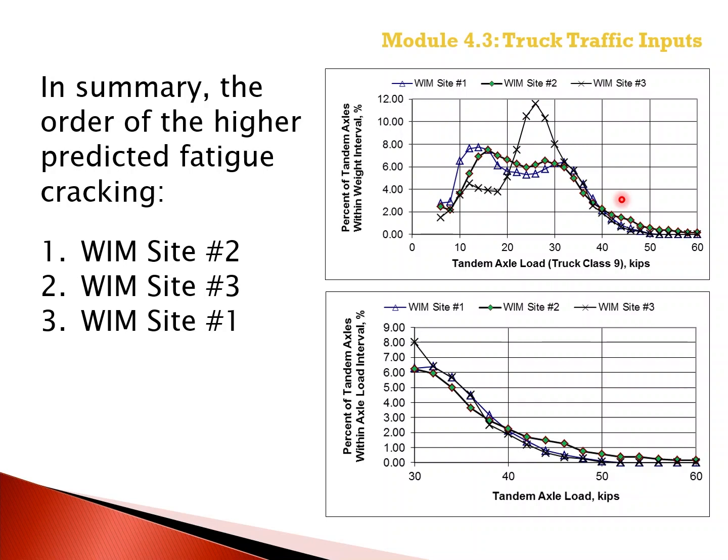So, do we have to have the same precision through all load levels for pavement design? The answer to that question would be no. We'd want the higher precision at the higher load levels to ensure we have an accurate representation of the normalized axle load distribution factors from basically the axle load limit up to include overloaded trucks that we know occur on our roadway system here in North America.